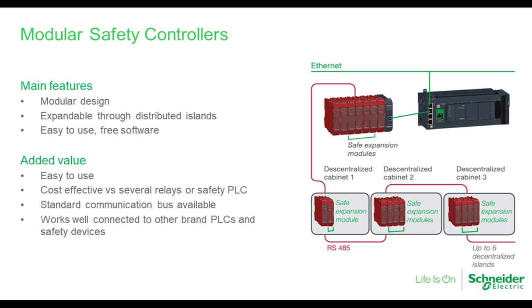They're both logical. Obviously, an engineer who would be working on this would want to consider the sequence of operation, and there's a measure of interoperability between these two components, but they're not in the same product, and they're lower cost. The codependency of these products is not as strong as with a safety PLC. So it's not always the right answer. I'm just mentioning this as being a lower cost way of dealing with a lot of medium complexity machinery where there's safety logic needed, where we tend to jump to the conclusion that we need a safety PLC. This may be a simpler way to do it in many cases.